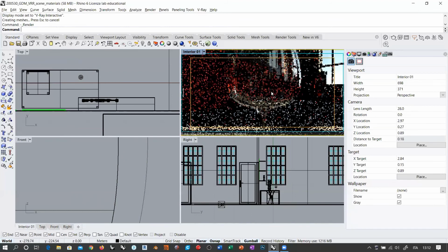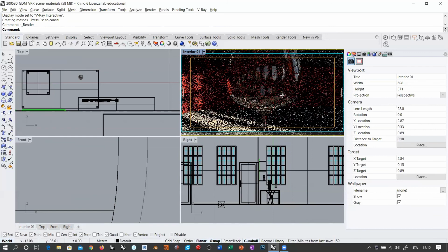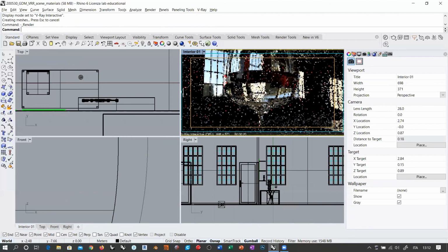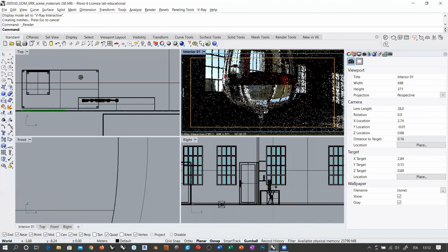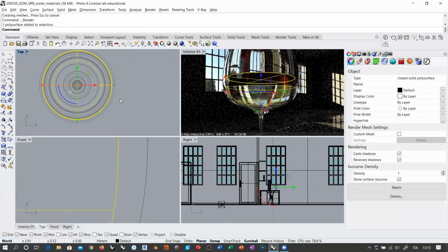But we should start to notice that there are some triangles happening now and then. I don't think that we are going to see this with these particular light conditions. There is a lot of reflection going on, and also the inner material is steel glass. There is something happening here. You might notice that there are some crispy areas. This is due to the fact that we have two overlapping surfaces, okay? So this is something that you don't want to have in your rendering.